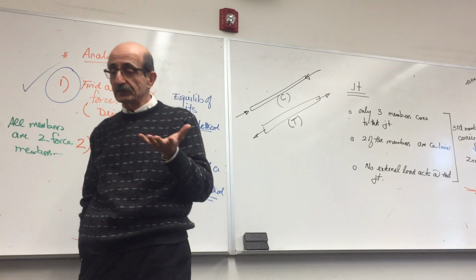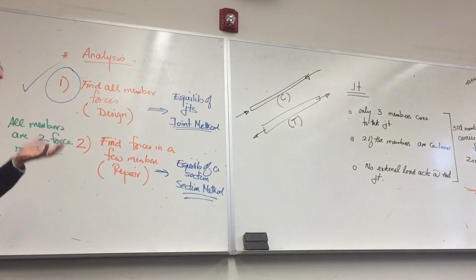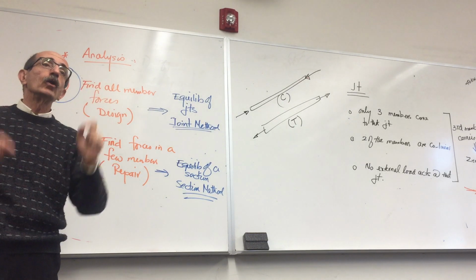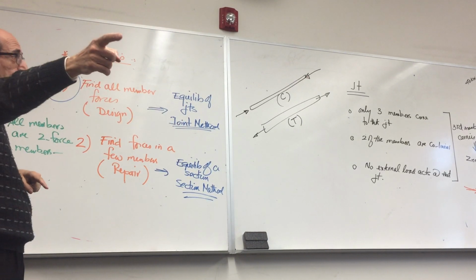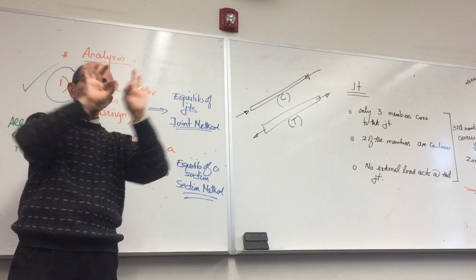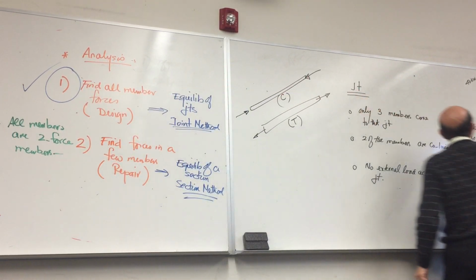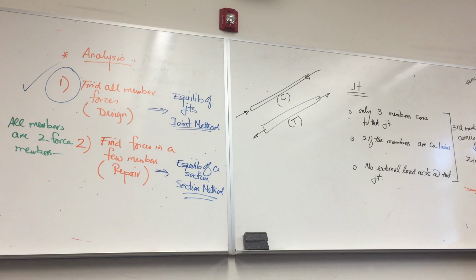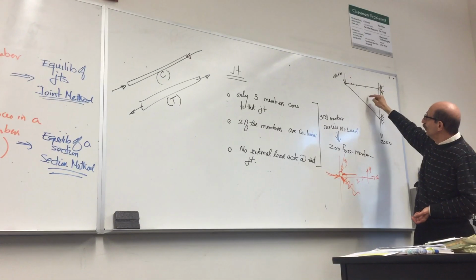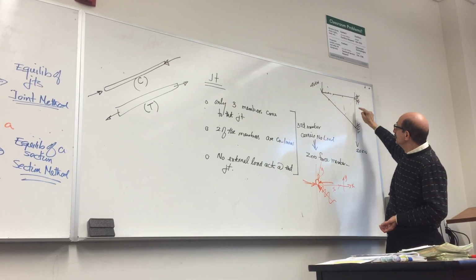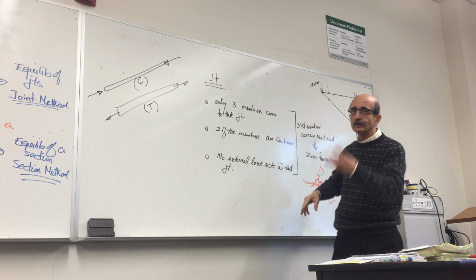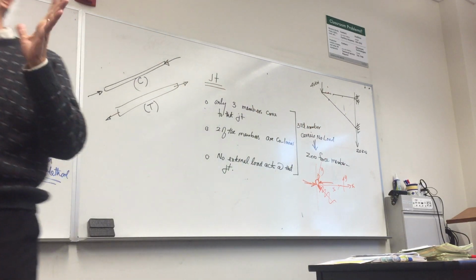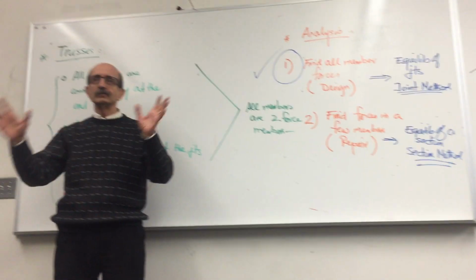So there are situations where you have a truss that you know for a fact where exactly the loads might be. In that case, you don't need that force. And in that case, getting back to your point, you don't need to have that pin. If these members are not needed, I have now just 3 members. I used to have what? 1, 2, 3, 4, 5, 6, 7, 8, 9, 10, 11, 12, 13. So that 13-member truss is now reduced to actually a 3-member truss. Okay, so that's very important. Any other questions before I start?